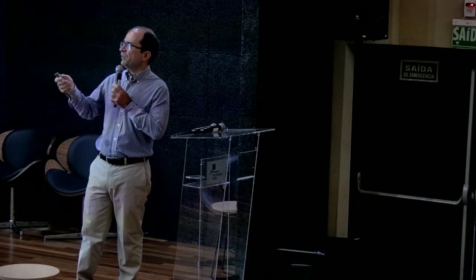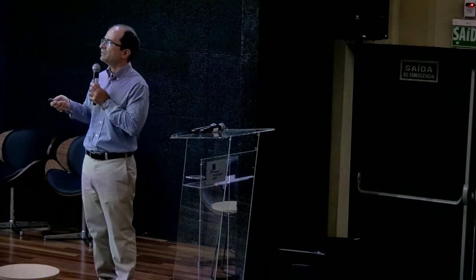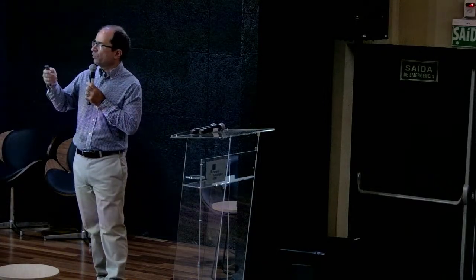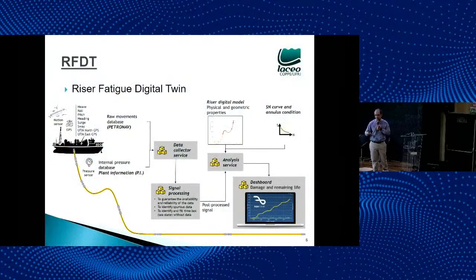So this methodology uses the motions measured at the platform and information about internal pressure at the riser at the platform, instead of using design considerations for this. So this measured data is collected by the data collector service, and these top motions need to be processed because sometimes the sensors generate spurious data, signals with mean values different from 0.